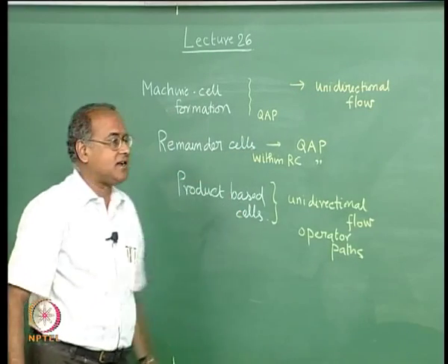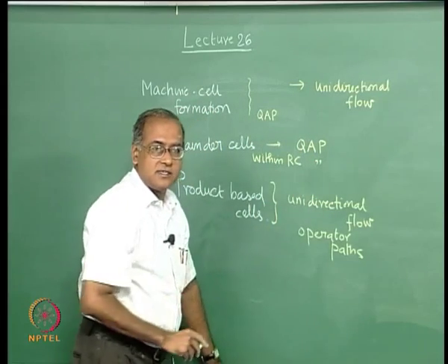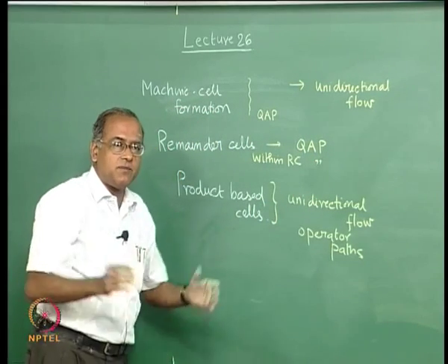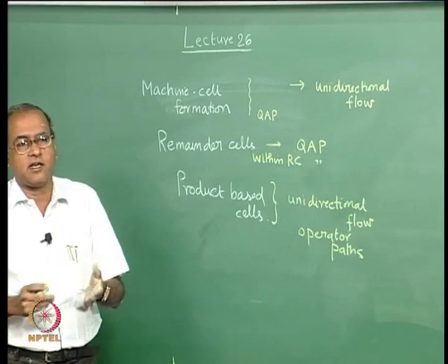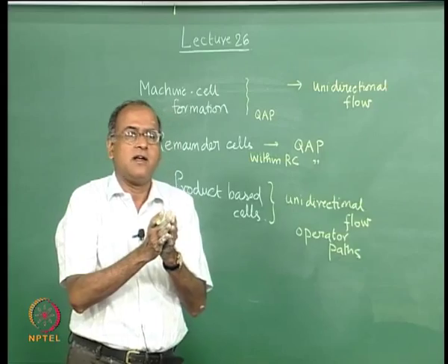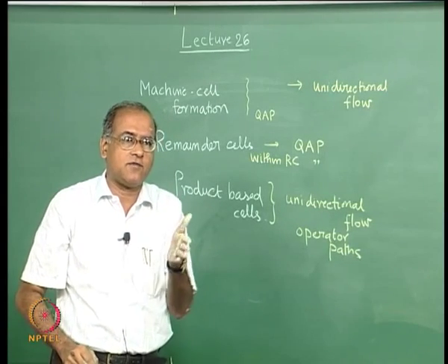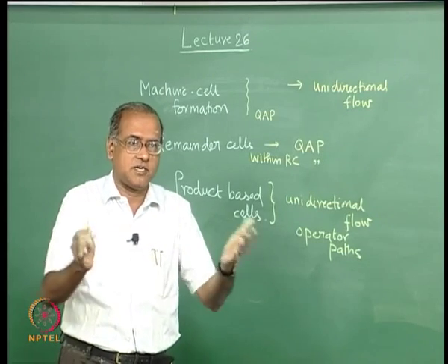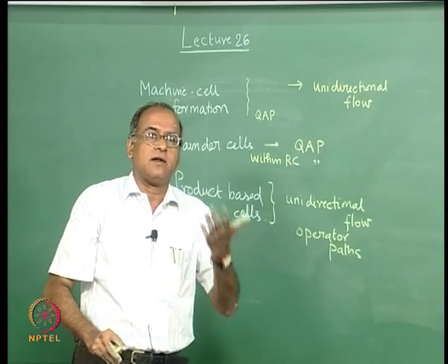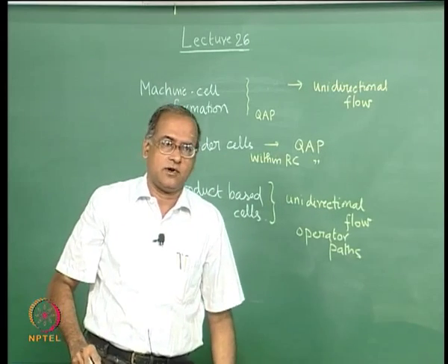The more important thing in all of them, particularly here and here, is space, to keep the machines sufficiently close, not too close, because you still need some space for some minimal work in progress inventory. Plus we also have to follow the regulations of minimum distance between the machines in a plant, but the less space that we utilize, the less inventory that we will hold.